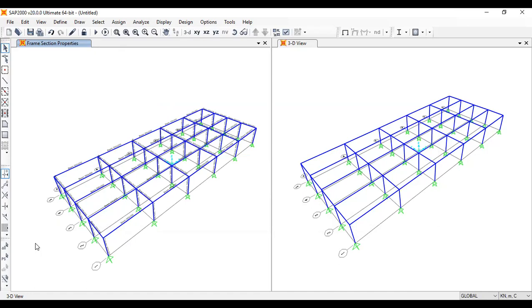One thing is the load patterns you define are coming into play when you analyze it. You analyze it for the load patterns you define. So if you analyze for that unit load, you will not consider any of the self weight. If you want, you can analyze both dead and unit load. One with self weight and the other one without any self weight. And where we define any external load, we define it using unit load.